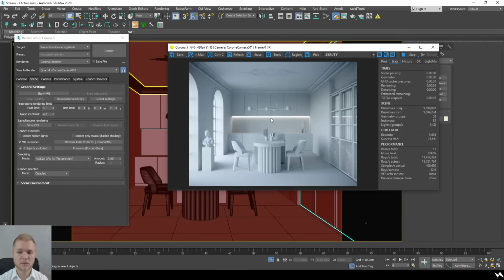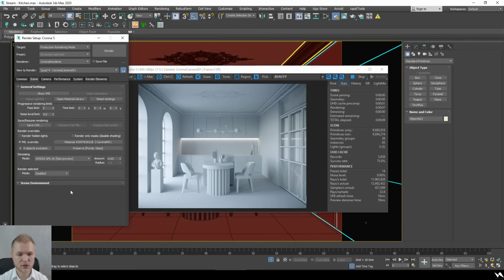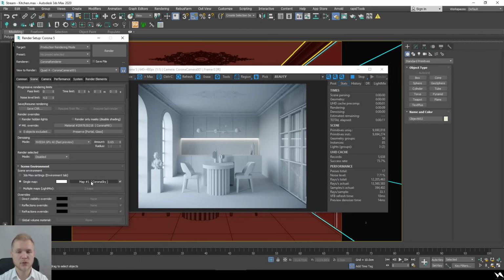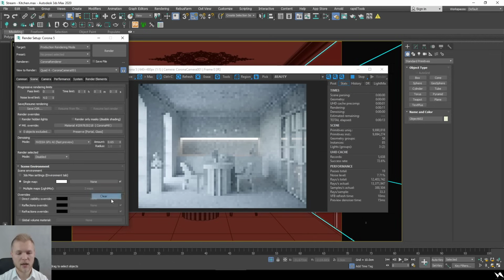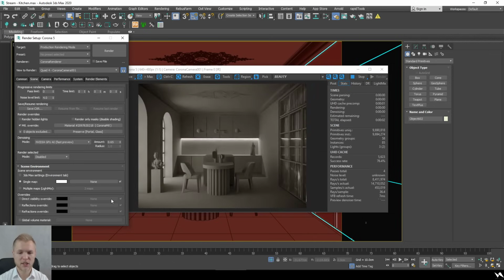And now let's explore our light setup, because as always, we try to use the most efficient techniques. So in this case, we created basically just two lights. One is the environment, which is Corona Sky on default values. Nothing else was changed because, as I said, we want to work efficiently and we want to work really on the easiest possible materials.